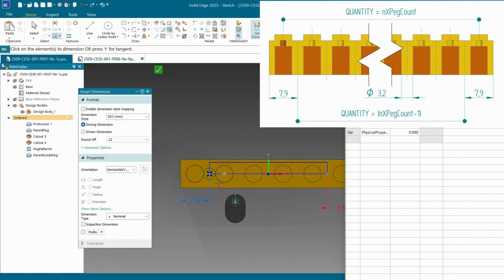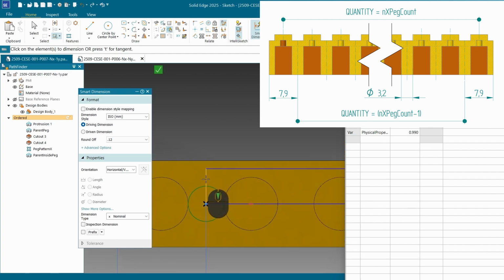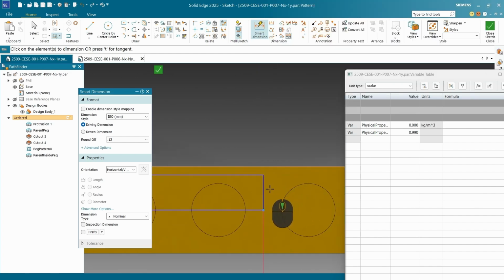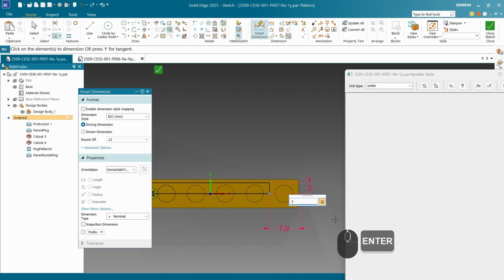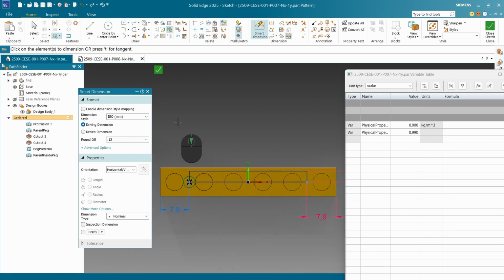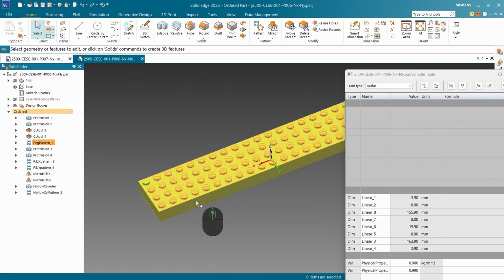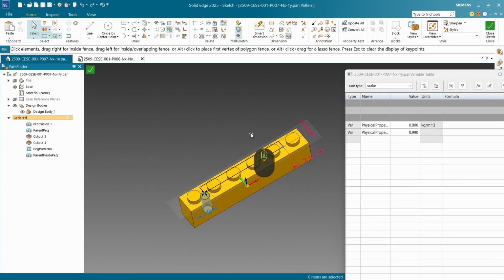And again, we're not too worried about the height of this rectangle, since our pattern will always have a single row of pegs. We are only worried about the X dimension. For the Y dimension, I can type in 3 millimeters, I can type in 3.9, it doesn't really matter. We'll never have a peg along here. We'll be using a separate part. We'll be using this part to create blocks that are more than 1 peg wide. Okay, so we're back to our 1 wide block.